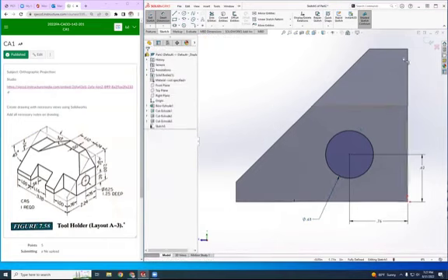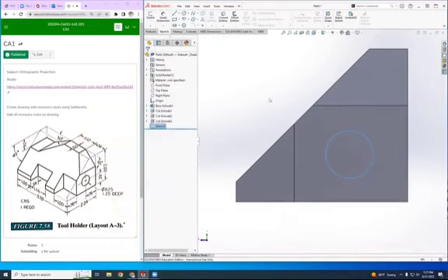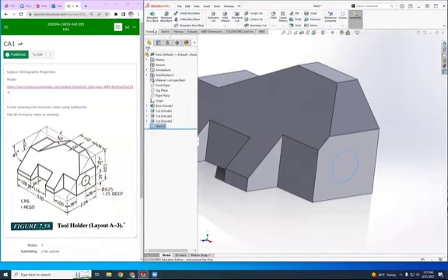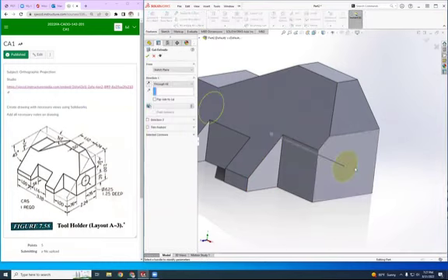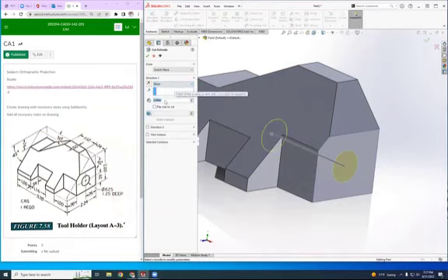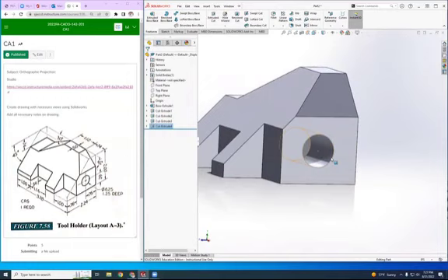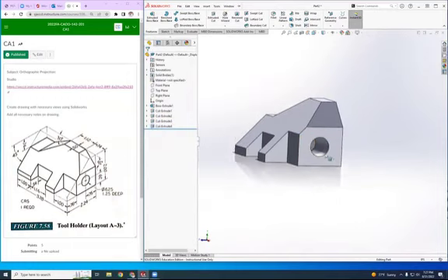And for the constraint sketch, now I need to cut it. Cut this circle, make a hole 1.25 deep. So I'm going to go to features, extrude cut, not through all. It's going to go blind. It's a blind hole, and that is 1.25. That's how deep it should go. And we call it blind. So there's your blind hole right there. This distance from here to here is 1.25.